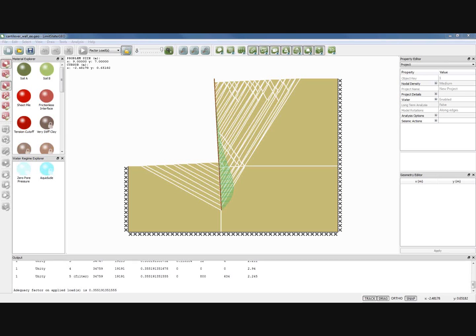There are various ways in the literature, people looking at how you can adapt or interpret ultimate limit state distributions to give you an estimate of serviceability limit state bending moment distributions. So concepts like mobilized strength and so on can be useful there, but the software does not do explicit elastic analysis. It's all ultimate limit state plastic analysis.